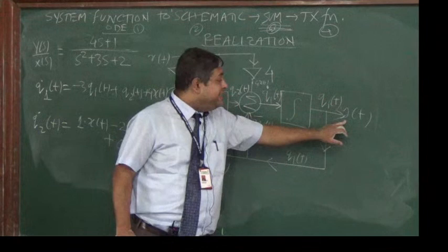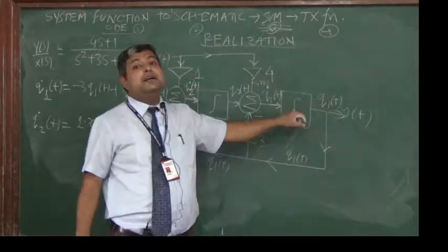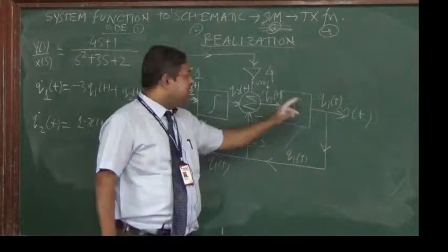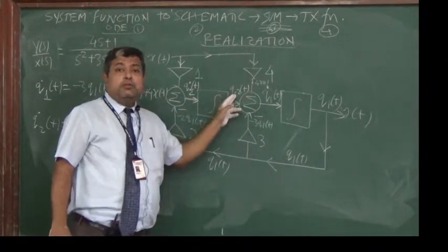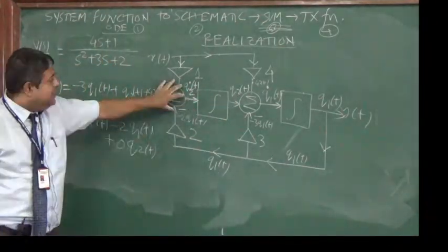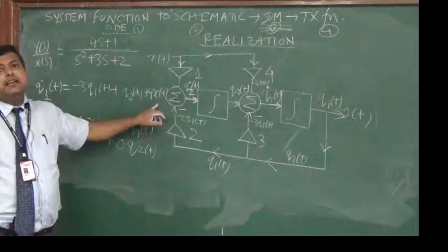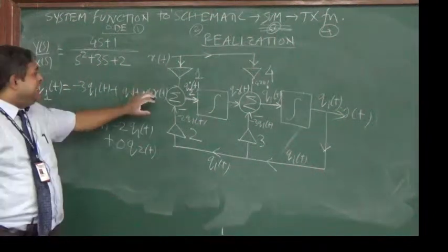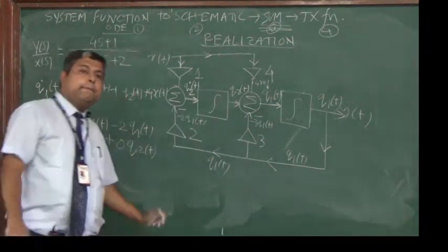T will be corresponding to q1(t). Then there will come an integrator. Before the integrator, if this is q1(t), this will become q1 dot(t). Then again before this summer there will be a q2(t). There is an integrator, and before this there will be q2 dot. There is a summer. If there is another integrator, here it will be q3(t), and then before this integrator, it will be q3 dot(t), and it will keep on going like this.